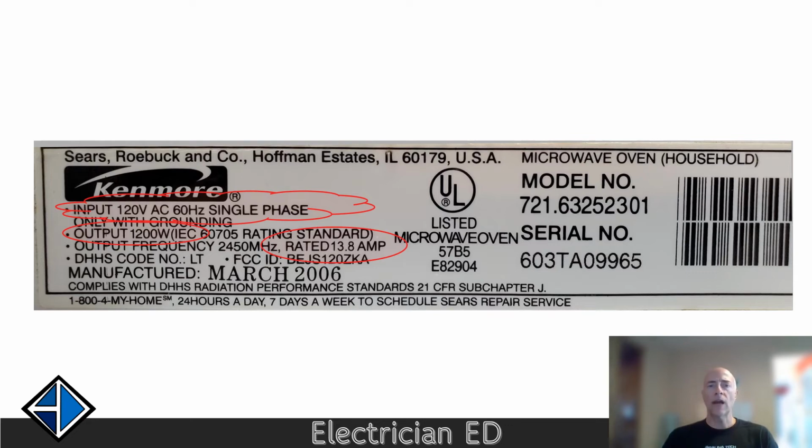Normally in the kitchen, dining room, pantry, breakfast nook, etc., remember you can only have 20 amp appliance circuits there. So any receptacles that are normally there could only be 20 amp circuits. This is the exception. And you'll find that in NEC article 210.22 and .23.